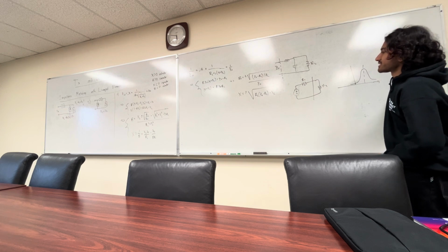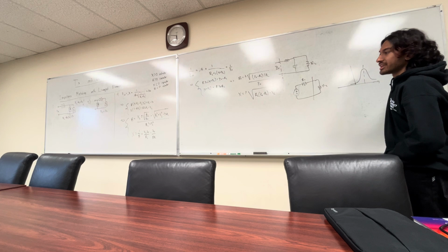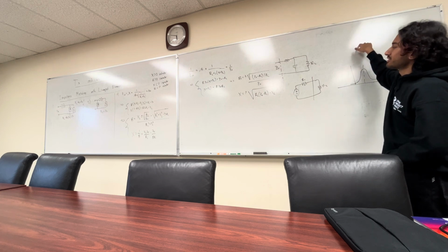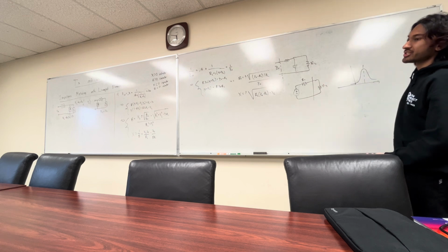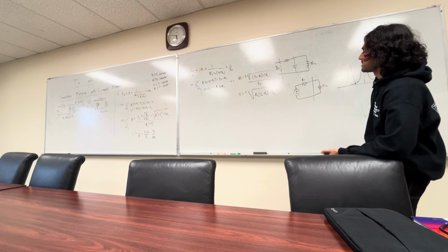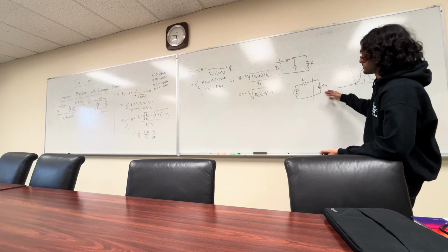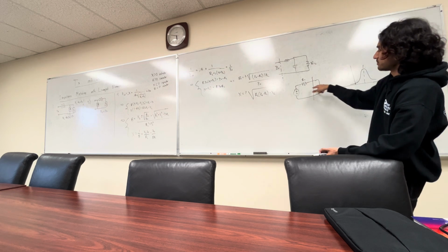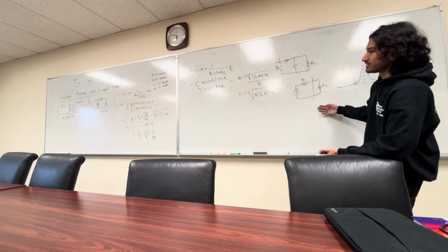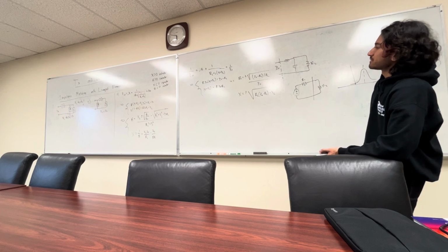Now, the downside is when you make a filter, you can choose any values to get a certain cutoff frequency. Here, the values you choose are dictated by conjugate matching. And the filtering is not so much a frequency response due to that as it is due to just this ratio here. Effectively, you get good characteristics from this.